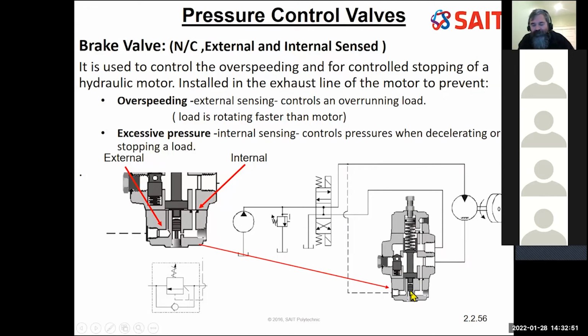A little bit of internal sensing to help maybe get this open. Well, remember we talked about with the counterbalance valve, that was a little bit inefficient, internal sensing. If I have the external sensing as well, well, we didn't have that before. I've changed the bottom of the valve as well to have both internal and external. So I've changed two parts of this valve in order to make it function.